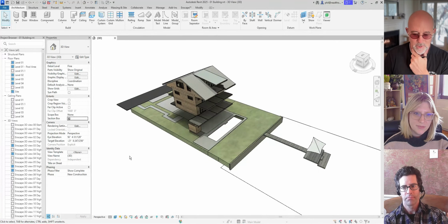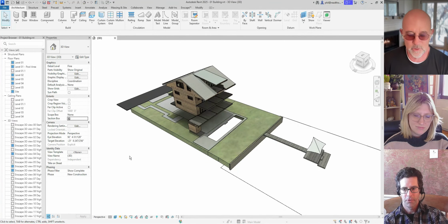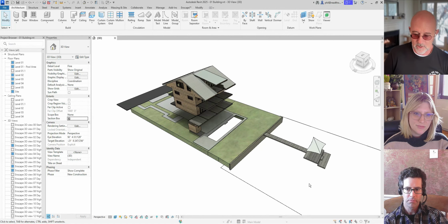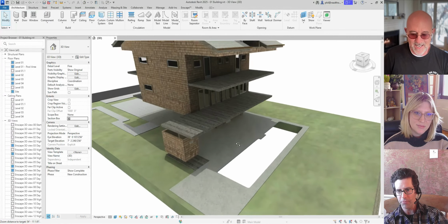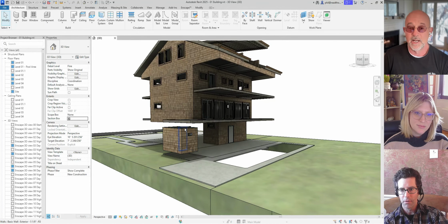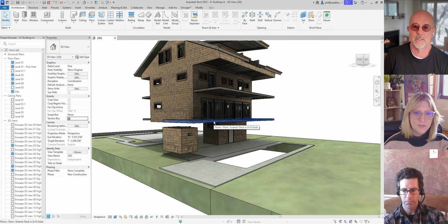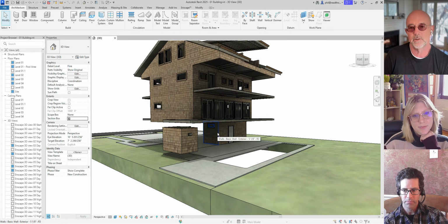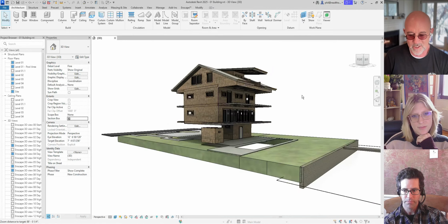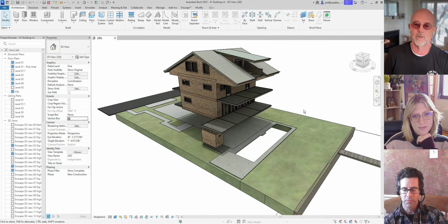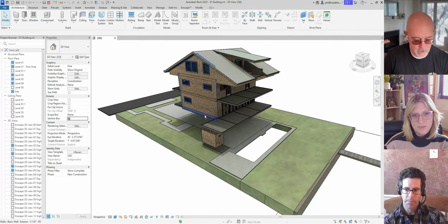Okay. So we do that. Oof, a lot of stuff goes away, and yet there's still some pieces over here. You still have a floating, probably a floor element or something. Well, there's an outdoor shower, and that's a containing space, but we don't need that. It's not a conditioned space. And then there's a storage room here that's not conditioned. What I was starting to do earlier was turn that stuff off, grabbing things and hiding elements, and I thought, well, this is too complicated. Why don't we just build a section box around what we care about?